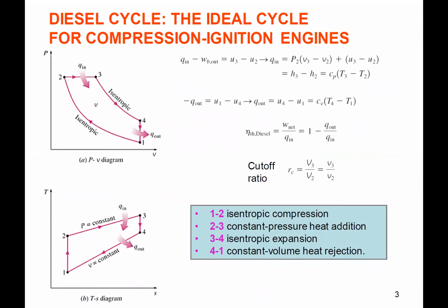Diesel cycle, still a closed system, right? It's an ideal gas, right? The big change is how we're adding heat, right? We still have isentropic compression,